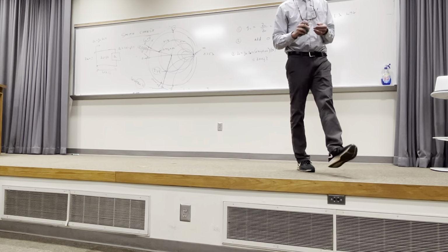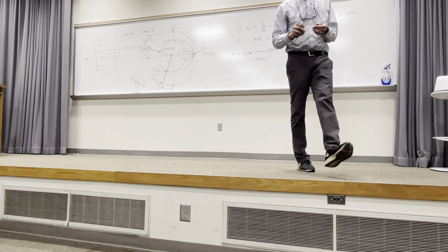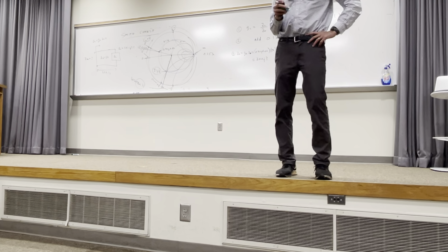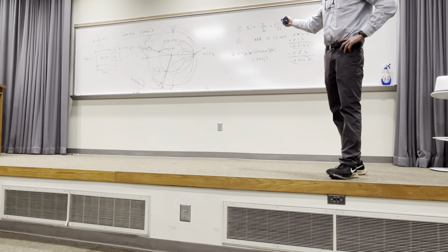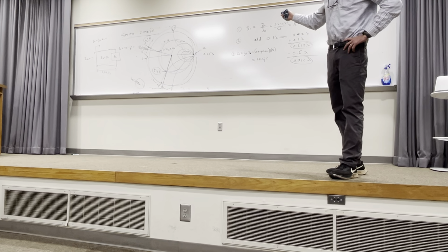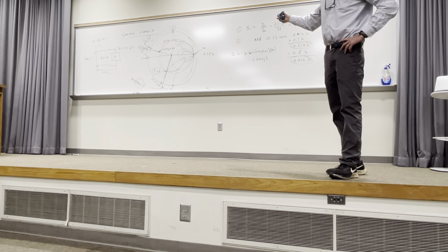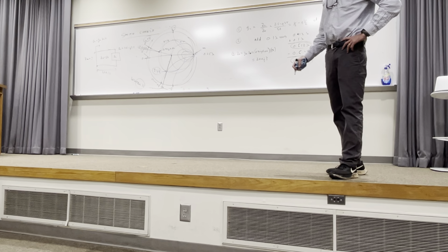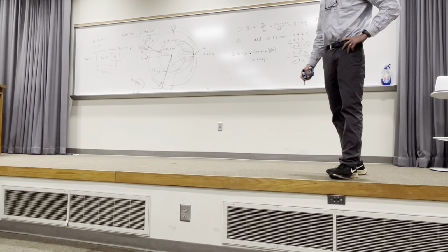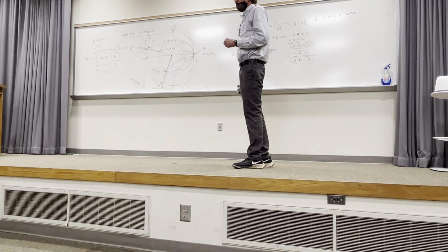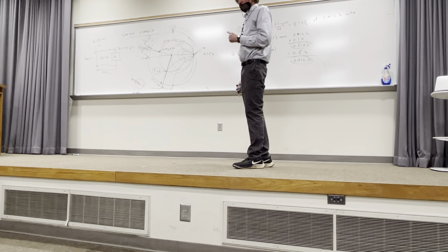Stop. What did we get on the prior problem? Wasn't it 19 point something plus j what? 0.19 plus j3.195. All right, you see how 3.1, we're close. Do y'all follow me? The error has to do with the thickness of your pencils, the ability to center things, and frankly, your eyes. But that is close enough for just about anything that you're gonna have to engineer. Anything else would be done in a different way. Y'all with me, class? So that's how you find the input impedance using a Smith chart.